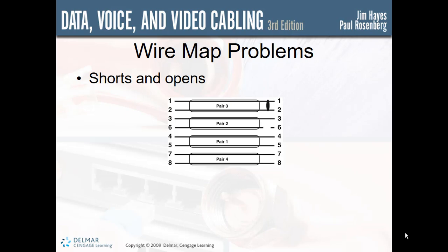Now, a short is what we're looking at up top, the first one, 1 and 2, where we end up having the two wires connected to each other, so they're shorting each other out. And then if we look at pair 2 with wire number 6, you'll see that there's a break in the line. So the wire never really made it to the end of the connector, and that is what we call an open. Okay? Opens can also occur due to cable damage.